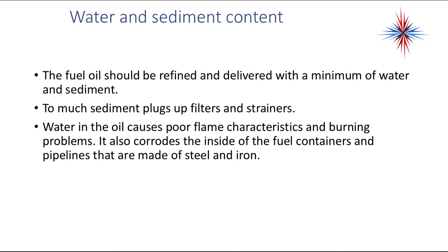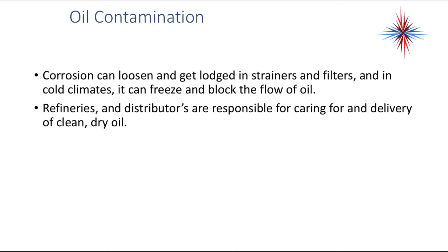Water and sediment content is another pretty important property of oil. The fuel oil should be refined and delivered with a minimum of water and sediment. Too much sediment plugs up filters and strainers. Water in the oil causes poor flame characteristics and burning problems. It also corrodes the inside of fuel containers and pipelines that are made of steel and iron. We do not want water mixed with our oil.